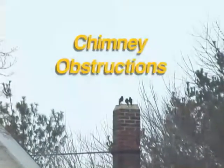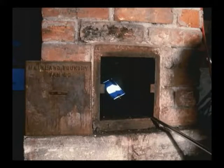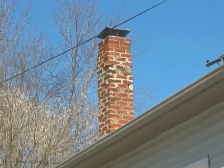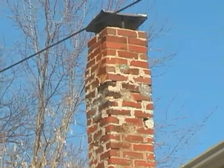Chimney obstructions. Soot, birds' nests, squirrels' nests, offsets or bricks, tile fragments, and debris caused by physical deterioration will increase the resistance to flow and reduce draft or even stop it altogether. Masonry chimneys can and do break down, and condensation is a common cause.